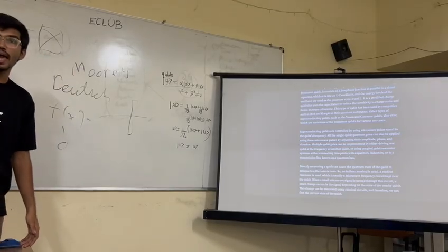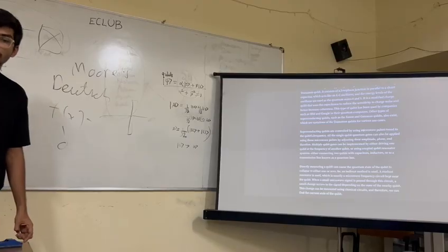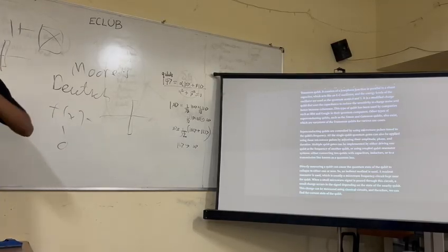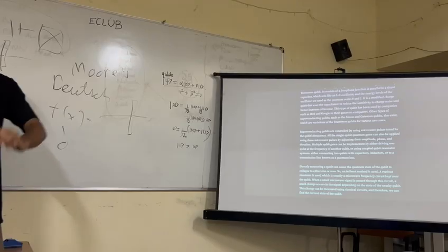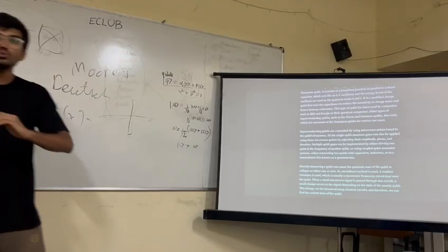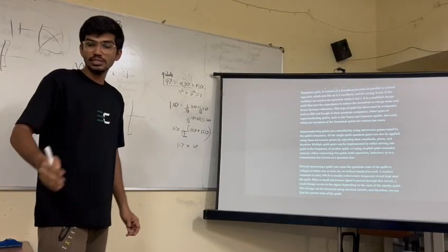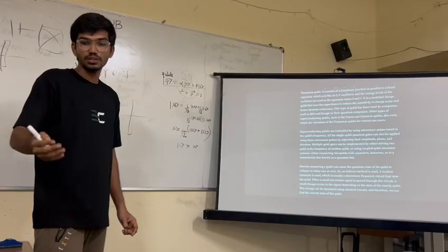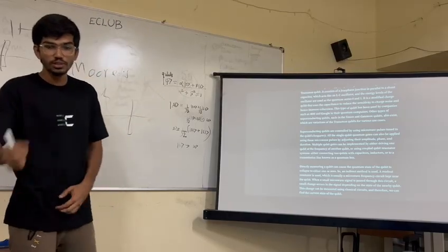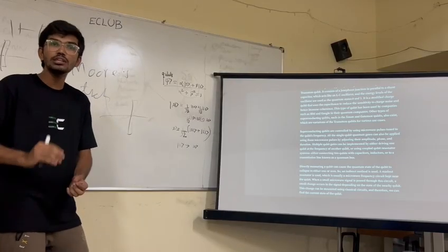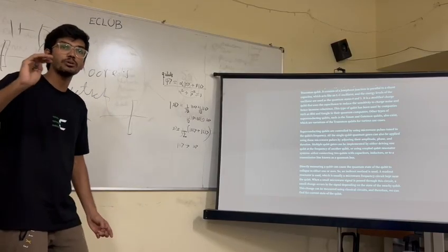An LC oscillator will have a frequency like that, but the difference is that the Josephson junction creates energy levels. So in order to create a qubit, we will be choosing the bottom two energy levels, and we will be checking which energy level the circuit is in. If it is in the lower one, it will be 0. If it is in the higher one, it will be 1.